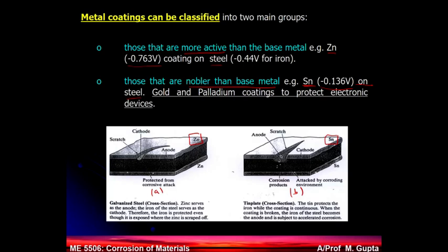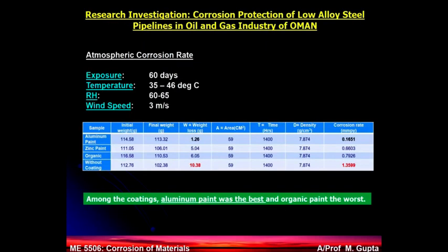Your scratch is a small area, so the area is small for the anode. So always the golden rule: anode should never be small. Again, it goes back to that shipping industry. Steel rivets and copper sheet. Bad news. Again, it goes to the same window falling from the homes. Aluminum, small anode and a big cathode. Never combine. Same thing is here.